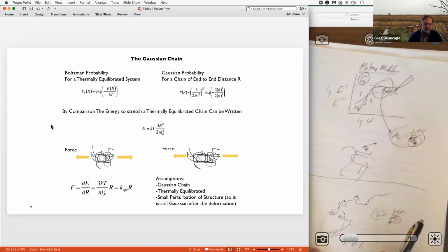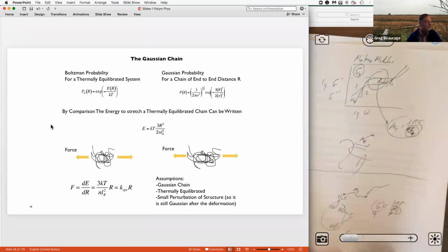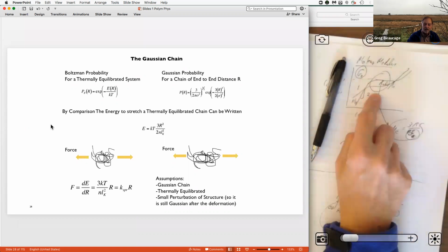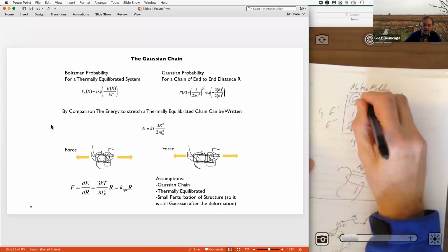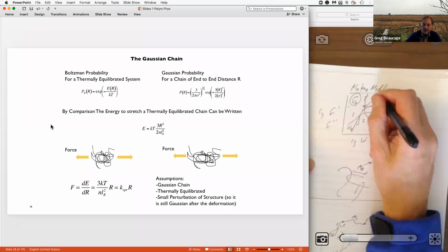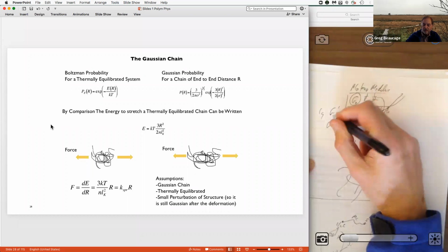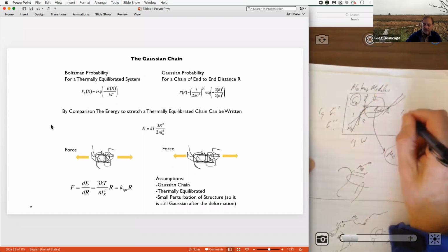So any kind of a gel or rubber, any kind of a soft material, you can figure out the structure of it just by measuring the modulus. And that's kind of the idea of this. And again, in the case of entanglements, the time-dependent modulus, the relaxation time is going to be related to 1 over that gamma dot, or 1 over the frequency at that crossover point in G prime, G double prime, or the turnover point for the log viscosity plot.